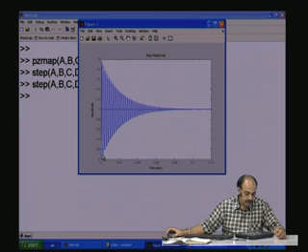And this damping is actually related to the position of the poles with respect to the j omega axis, how far it is with respect to the j omega axis. And this oscillatory nature, as we were discussing, the frequency will depend upon how far it is from the real axis, that is, what is the projection on the omega axis.